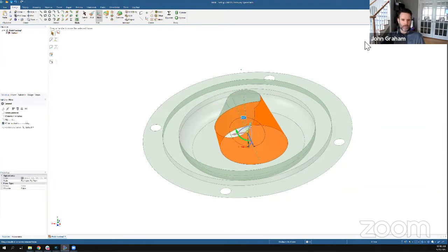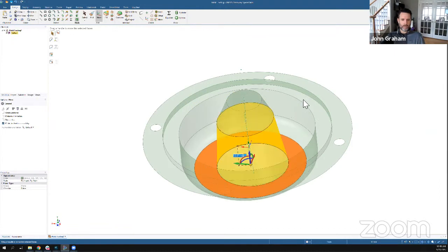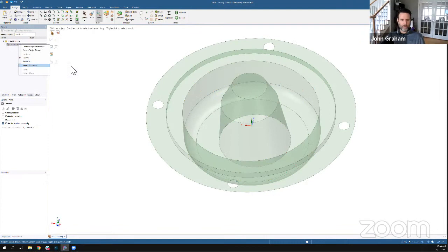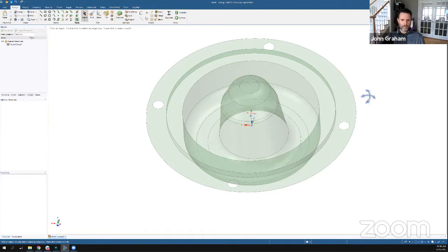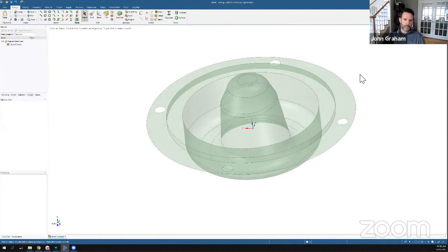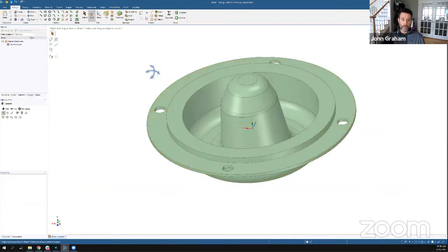I mean, I could go something crazy, but let's make a little nominal change right there and maybe drop down the height of this thing. There we go. That looks a lot better, definitely different from before. I'll reattach all those rounds. I think that looks good. We'll go ahead and put a thickness back on that of 2 millimeters, and I've got a brand new part.